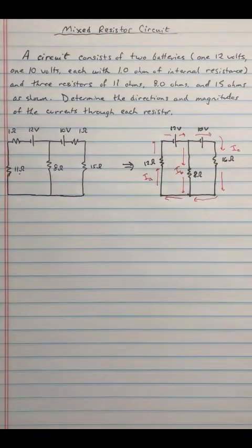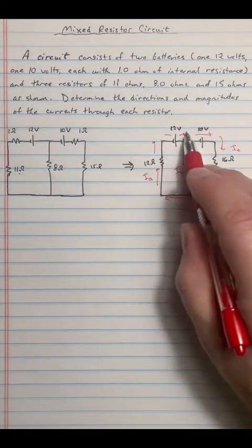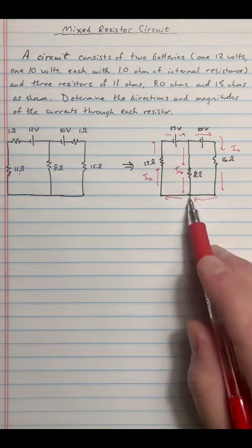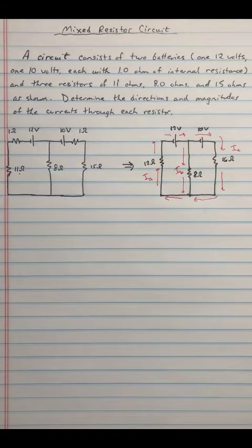Now, let's suppose that I've guessed incorrectly. Let's suppose that instead of going in this sort of clockwise direction I've got sketched here, it actually is going counterclockwise. And maybe that happens. Well, if we do our solutions properly and I solve for the amount of current flowing, that won't change the amount, it will change its sign. So suppose I solve and I find a current, and by the way, this won't be the answer.